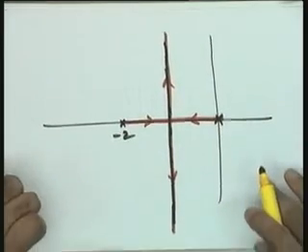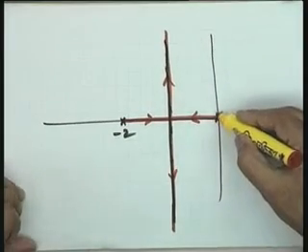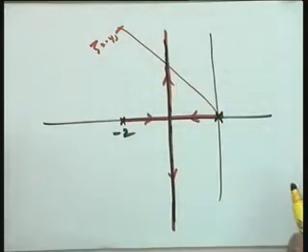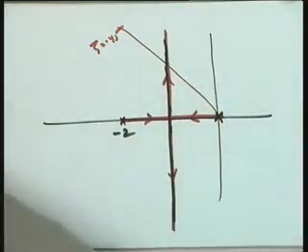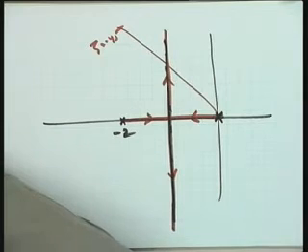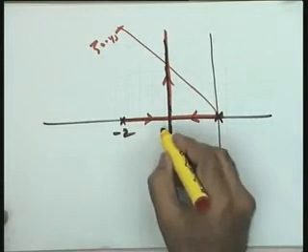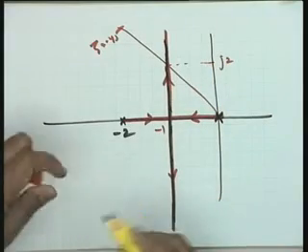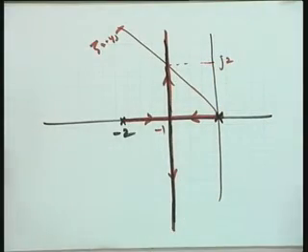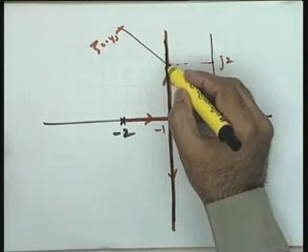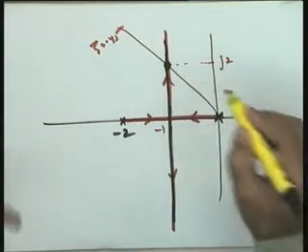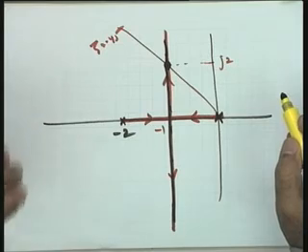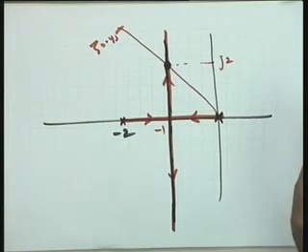Please locate the closed loop poles. The zeta equal to 0.45 line has been drawn over here. This line gives you the pole locations as -1 plus minus j2. Okay, these are the locations please. Now this particular point is on the root locus of the uncompensated system, and it satisfies the transient performance requirement.